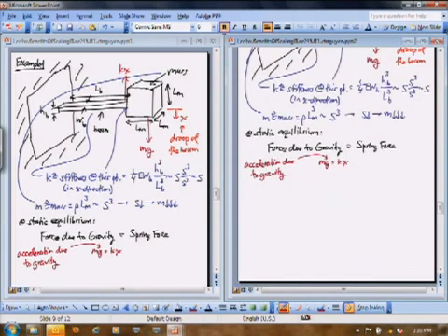And so I know that as I scale m with dimensions, if I'm scaling all dimensions, then m I said was going as s cubed, k is going as s. So that goes as s squared, which means that as I scale s, the amount of displacement x, the amount of droop that I get, is going to become smaller. So let me do that in words. As dimensions scale smaller, the droop, x, goes down.